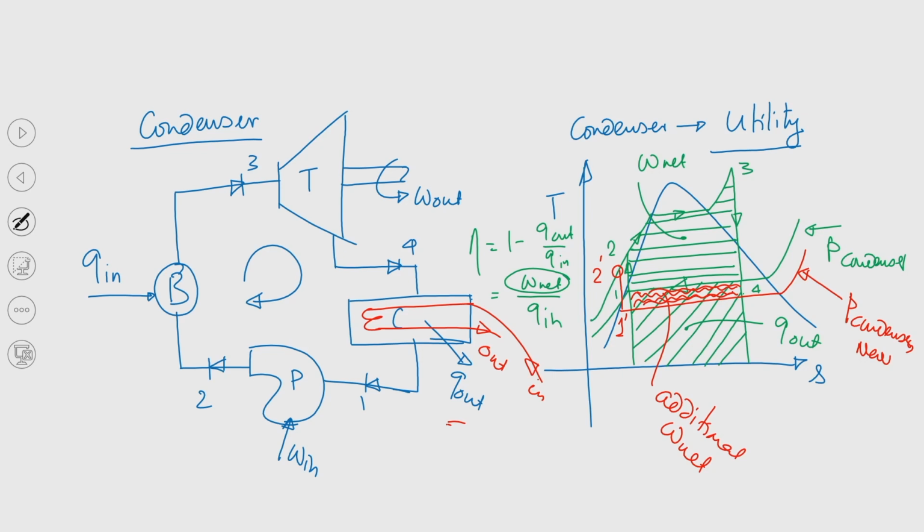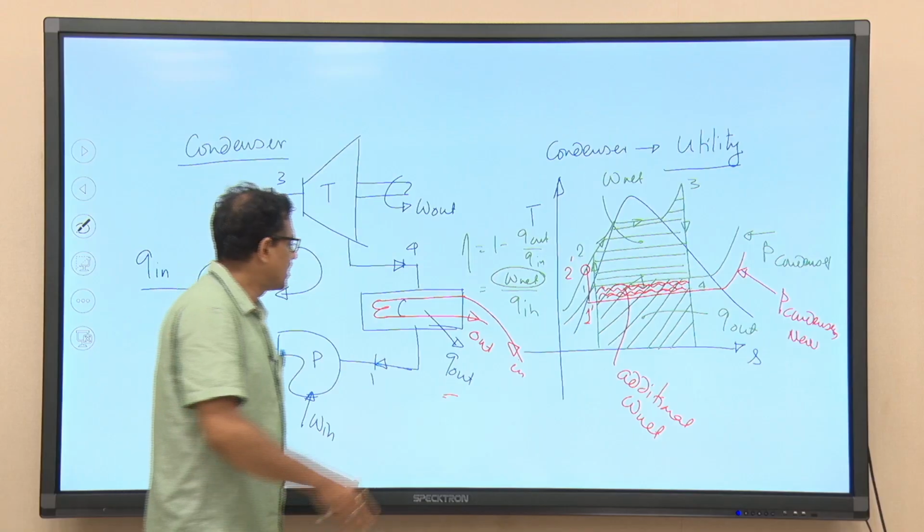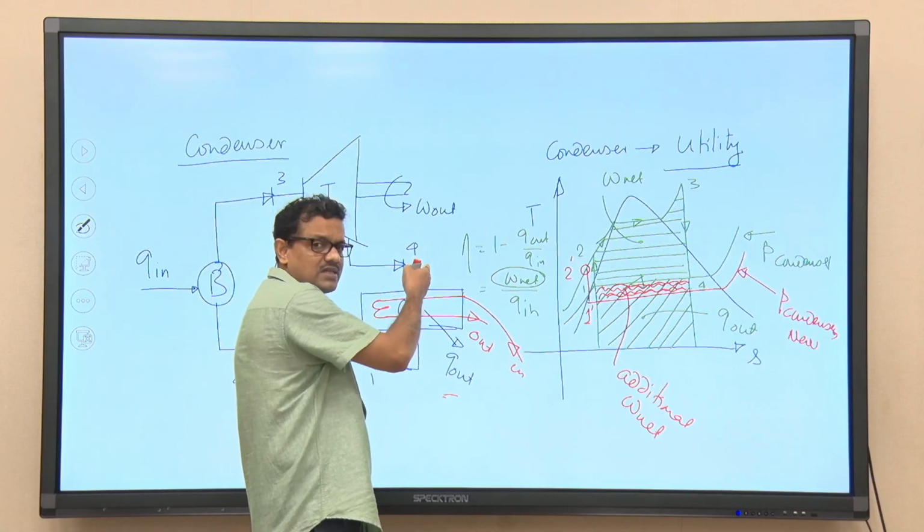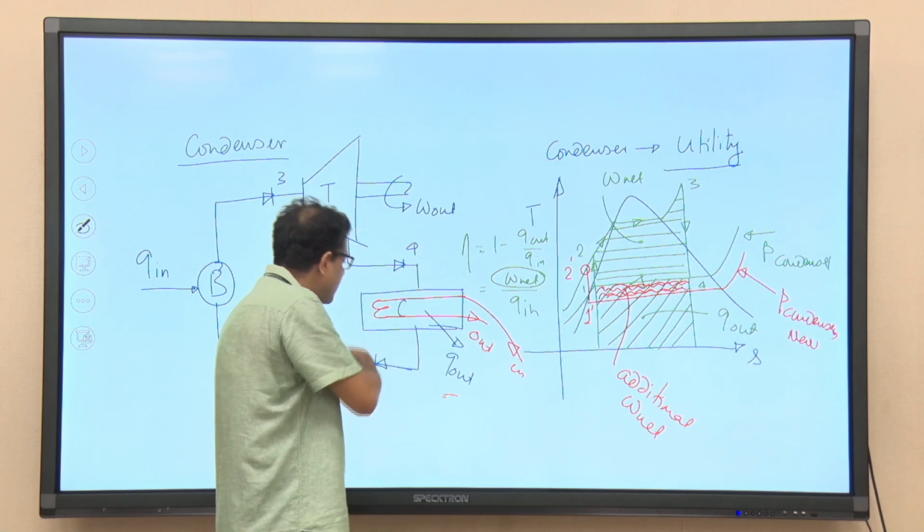Now, if it is indirect type, that coolant is coming through the pipe and steam is allowed to pass over the pipeline, I think coolant pipeline. In that case also we will be having heat exchange phenomenon, and because of this we can reduce the temperature of the steam, and that condensate will be again pumped back to the boiler.